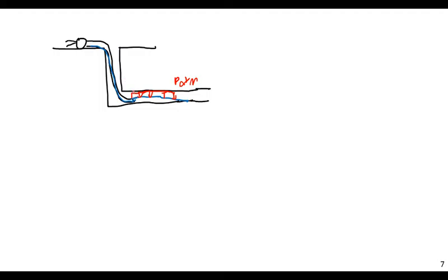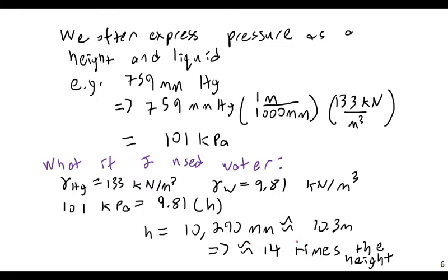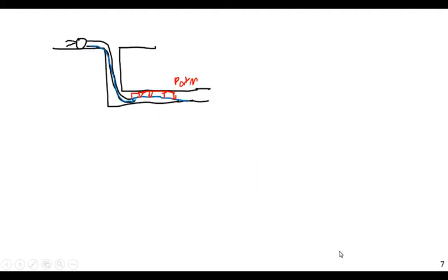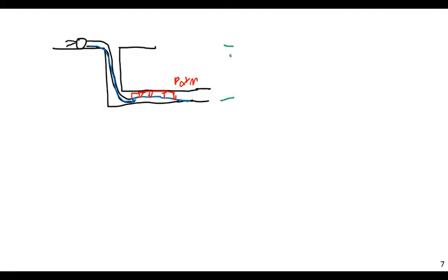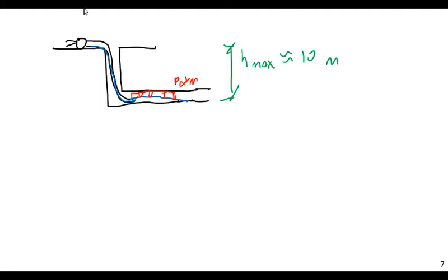And the reason is that atmospheric pressure can only push a column of water so high. In fact, it can only push water to a height of 10.3 meters. This type of system has a max height of approximately 10 meters. If you make this any longer, you're going to start drawing vacuum, and you'll just be pulling out a bunch of water vapor, which pumps tend not to like. It tends to damage the pumps. They tend to make horrible, god-awful sounds, and you know something is wrong immediately.